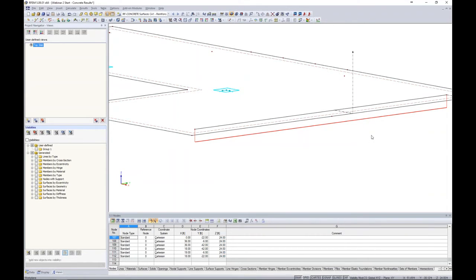So the question is that these little rigid links have full fixity to transfer moment, shear, and axial forces, but remember, we're trying to alleviate these moment forces being transferred from the slab to the beam, causing high torsion within the beam. So how can we automatically do this without modeling individually these little rigid links, what we may have to typically do?